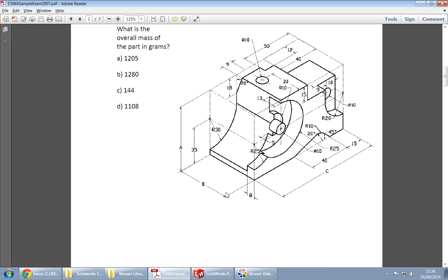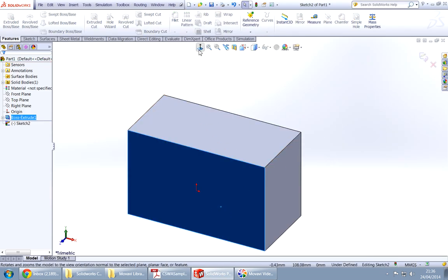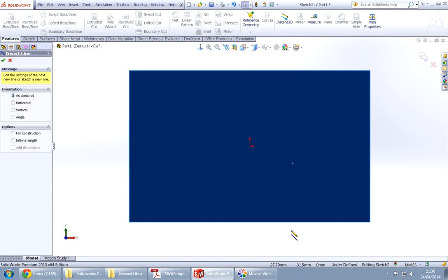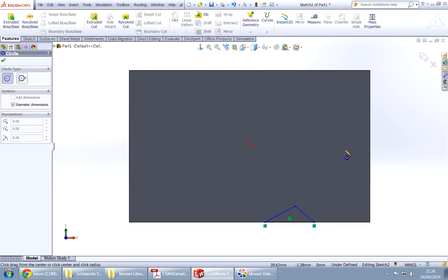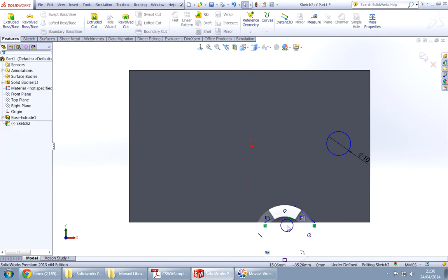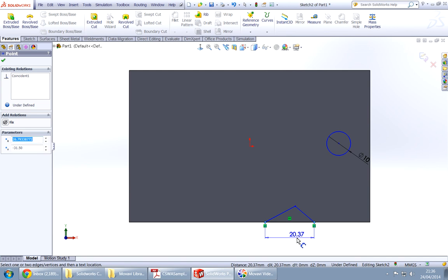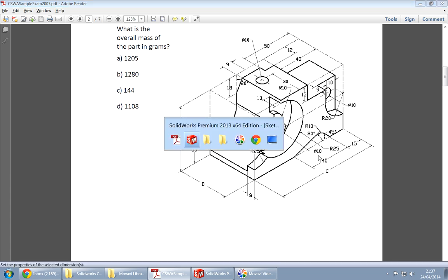and now we're gonna make this hole and another hole here. So go sketch, draw a line, like this. 10 millimeters circle, then dimension is 40. Oh, sorry, 40. One angle is 20, the other is 45.